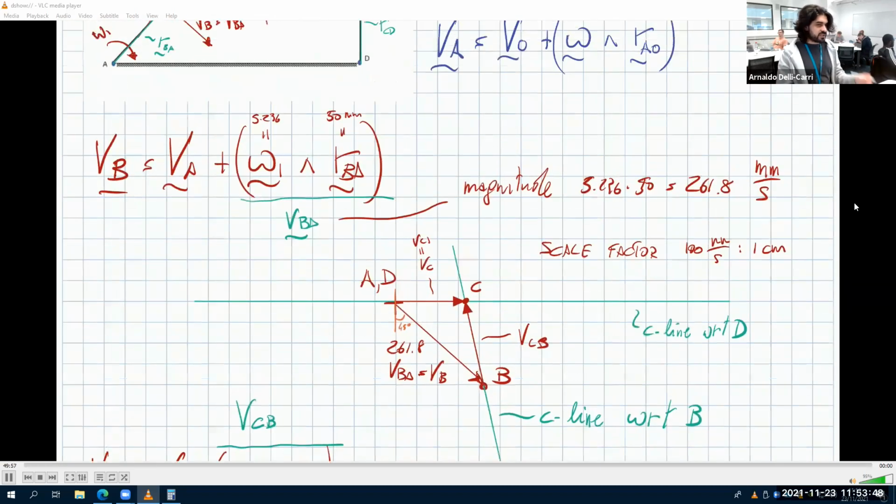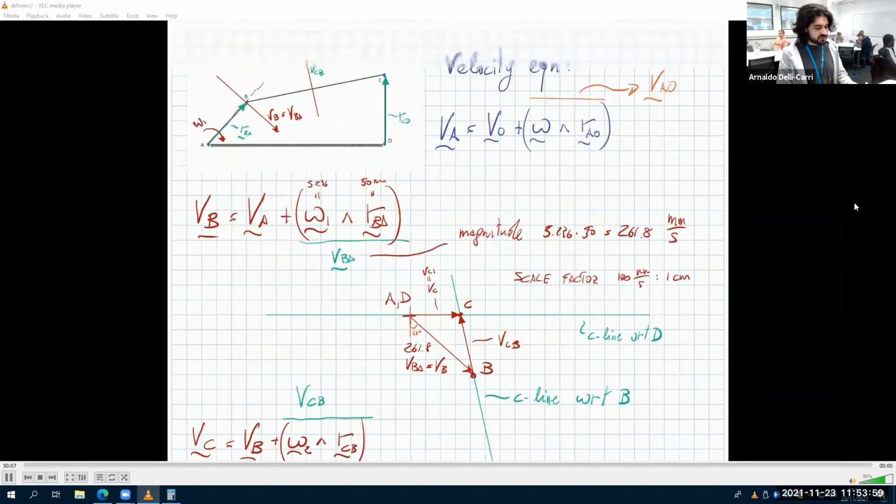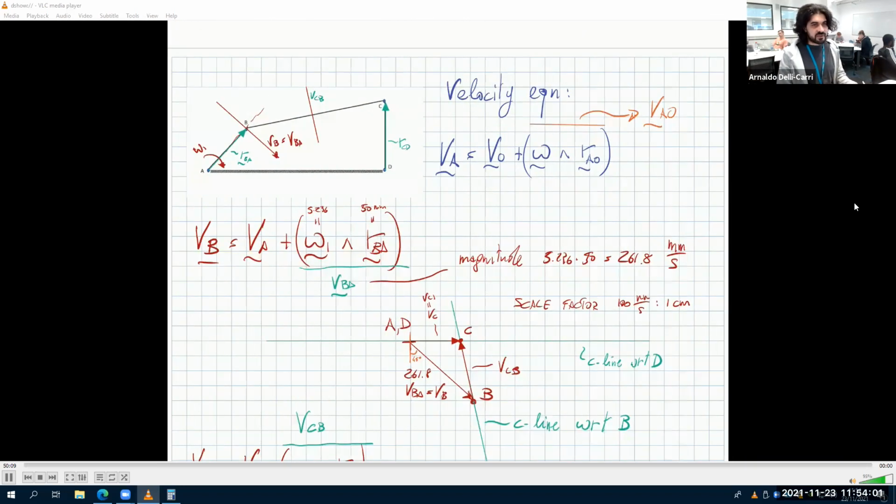I mean, you don't need your lines perpendicular to the space diagram. Yeah, exactly as I'm doing it. You can do it on paper. It's very easy. You just draw a line that is perpendicular to this, because in the paper you will be given the figure and the blank space to produce the velocity diagram. So you can definitely find the perpendicular one.